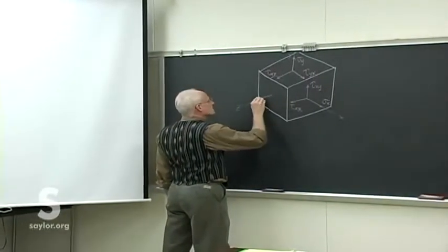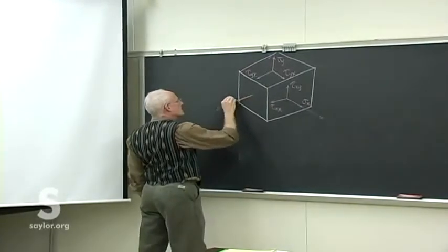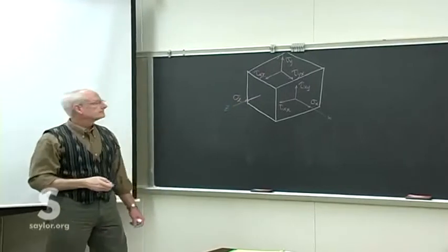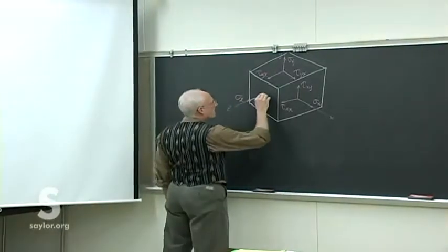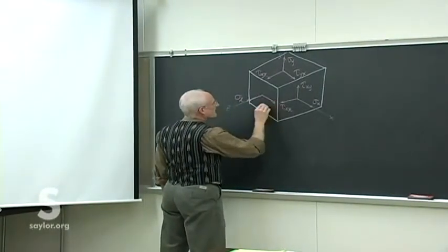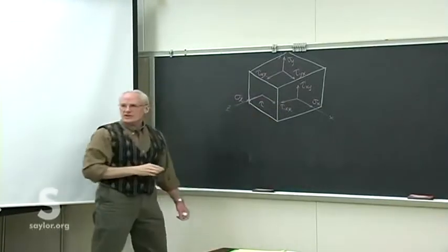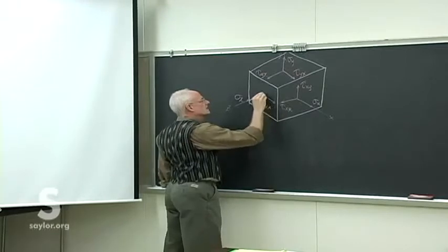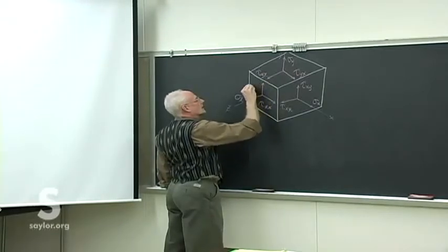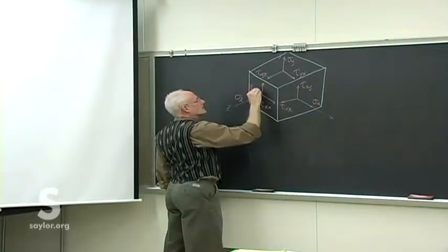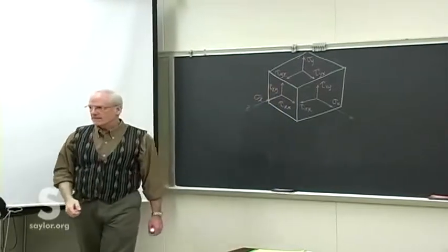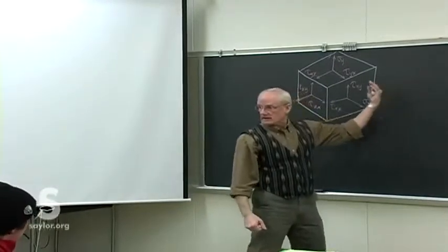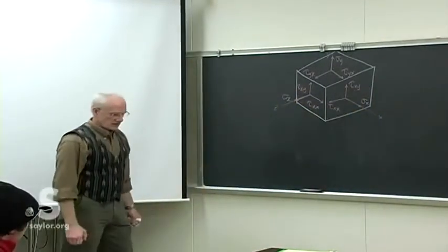And then there's also a normal stress to the Z faces, and a shear stress on these Z faces, one in the X direction and one in the Y direction. And then again, of course, on the back Z face, that I'm just not going to bother drawing.